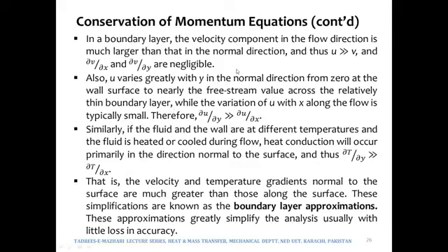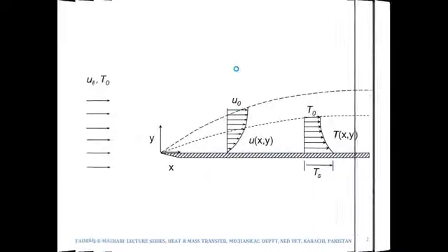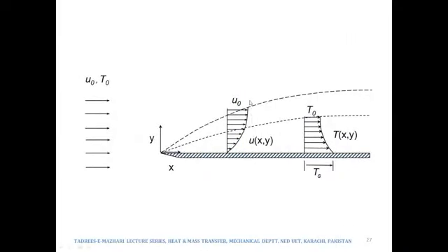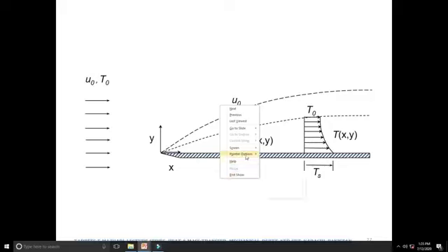If you take a look at the velocity profile, due to the no slip condition, if the plate is at rest, the velocity of the very first layer of fluid which is in direct contact with the surface would also be 0, and we have discussed no slip condition previously. So the velocity at this point would be 0.